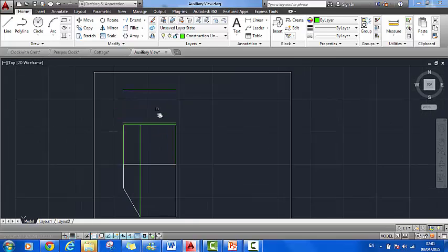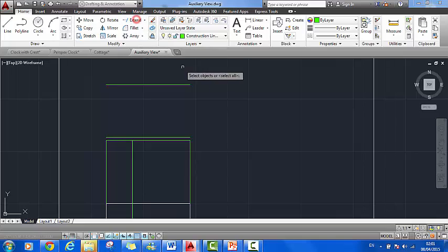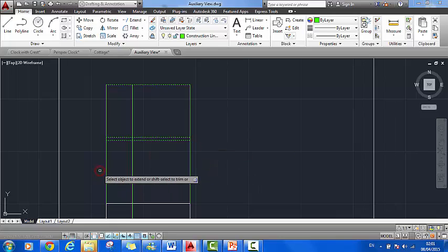That's at 50mm. I now want to extend these construction lines once more. Okay, so now I can go back into my drawing views and go over my construction lines that I just created.